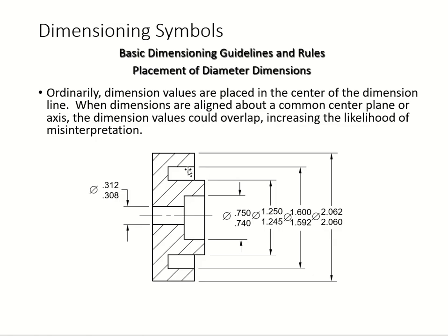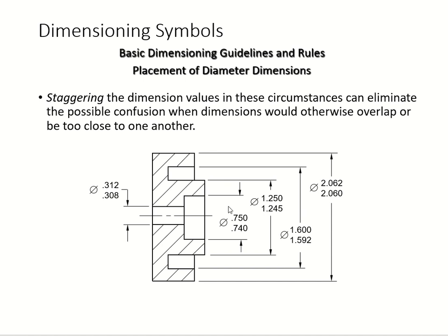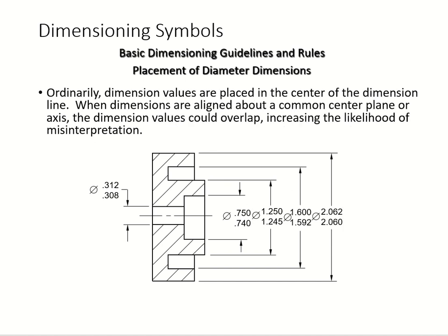Another part, this is a section, yeah, it's a cut part. We do the same thing, follow our dimensioning rules, smaller in, larger out. No space, so we're gonna use a dimension out and value out, dealing with the cylinder, so don't forget your diameters. The same thing, and we call that staggering, yeah, that's showing you a different placement of dimensioning.